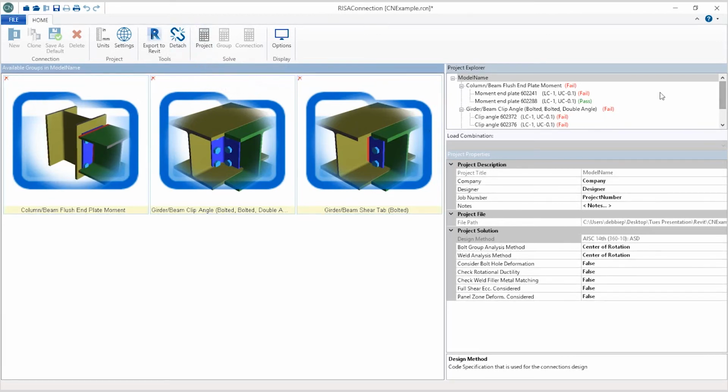And then it gives us a tally on the right side, fail, pass. I can see that listed there if it passed or fails. And then it gives us a code check in there with the load combination here that's governing. So ours are actually failing, but their code checks are under 1. So that always means it's a geometry problem. So we can start kind of addressing that one by one.